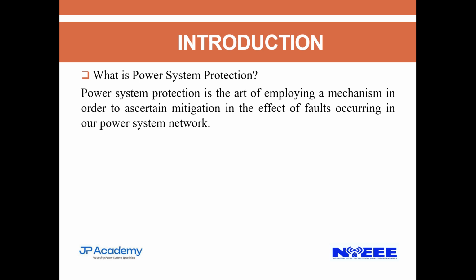So these are the four objectives. Firstly, we need to ensure we are isolating the fault. Secondly, we need to ensure we are isolating only the fault. Thirdly, we need to ensure that we are isolating only the fault as quick as possible. And lastly, we need to ensure that we are isolating the smallest unhealthy portion of the system.